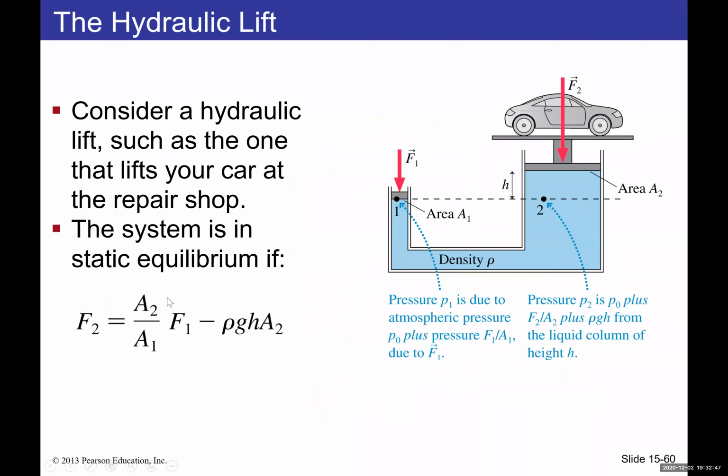All right. So one of the things we have here is known as Pascal's principle, or Pascal's law. And this deals with generally a liquid or fluid that is enclosed in some kind of system. It could be enclosed in a tube, or for example, your toothpaste, enclosed in a container. When you press at any part of your toothpaste, all that pressure transmits everywhere. The idea for Pascal's principle is this: if you have an enclosed fluid, then the change in pressure transmits everywhere without changing or diminishing its magnitude.